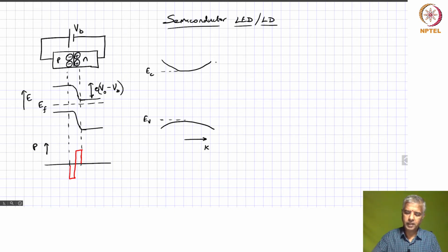Nevertheless, what we are trying to track here is actually the transitions, the recombination of your electron with a hole. So let's actually look at this in a little more detail. To look at that, we need to now look at the specific energy levels within this band, and we know that the energy levels are closer to the band edge.